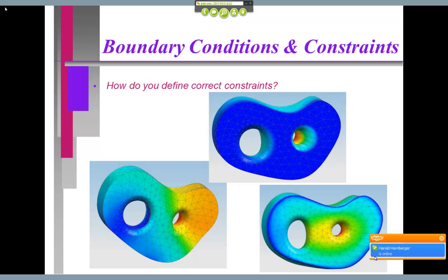If we look at the lower left, how can we think about that as being constrained? Well, again, it's locked into a pipe or it's on a shaft, and one has been heated, the other has been cooled, and it's been force fit, a shrink fit onto a shaft where this thing is going to be held rigidly on the inside.